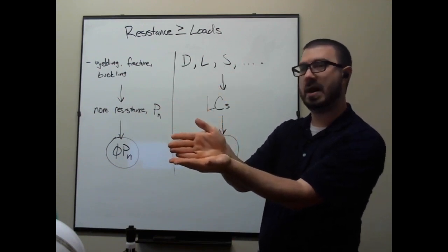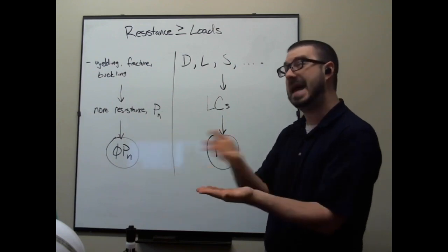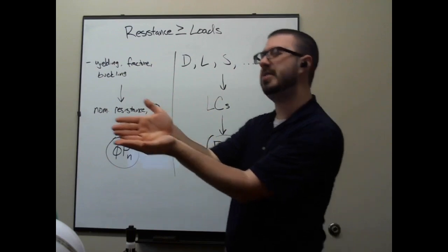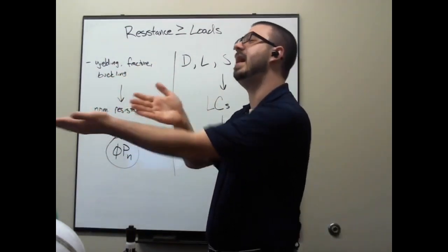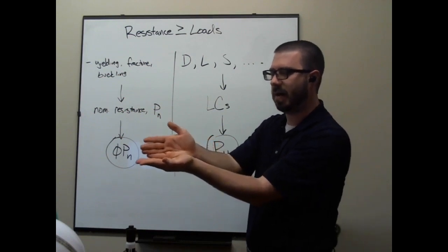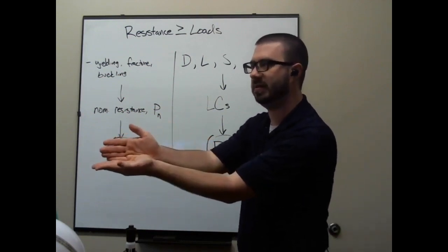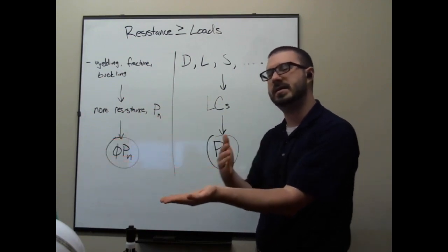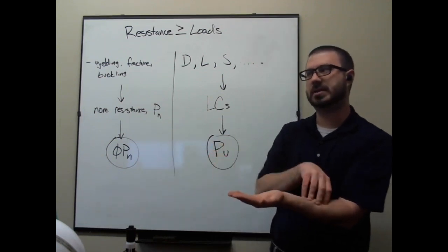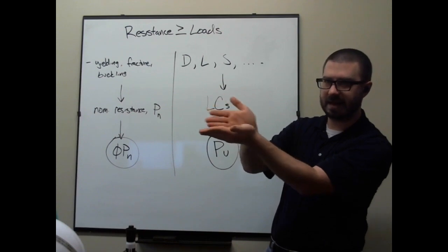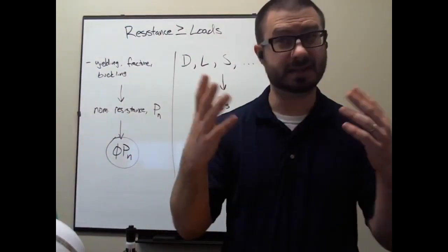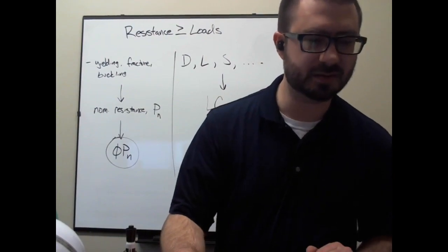When I yank on that member, I'm not yanking on the entire angle, I'm only yanking on part of it. So the other part of it is kind of lagging behind. As I yank on it, my left hand is wanting to receive the load, but the right hand is sort of lagging behind. It takes a little while for those stresses to propagate throughout the section. And because my hands are doing this, it's kind of like an internal shear going on in the section. That's why we call the phenomenon shear lag.